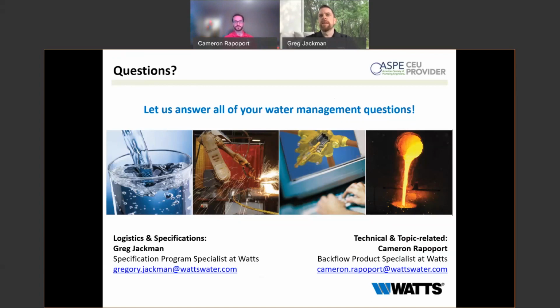If the building has an FDC, does it make it a high hazard because it could be unsure if the water from the truck could be from a dry hydrant source? That's a great question. So I know in general the existence of an FDC will not make it high hazard. And again, I'm not your local code official, but it depends on the surroundings.